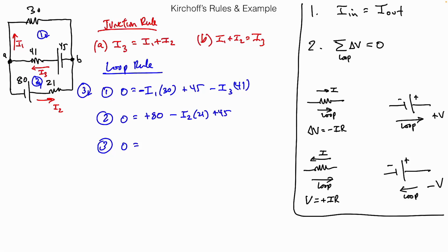All right. How am I doing so far? I started at point A and I got to the 80 volt battery. How'd I do on my sign? Are we good? My loop direction is taking me through the battery from its negative to its positive side, right? So that's plus. All right. Current and loop through 21. Same or different? Same, so negative. Okay, got the negative on there.